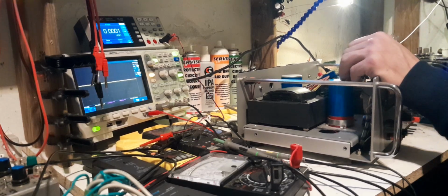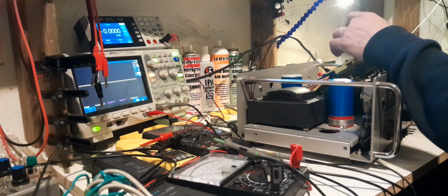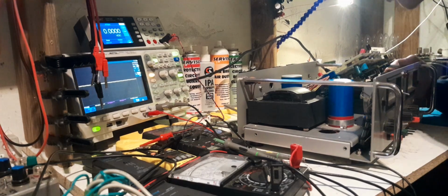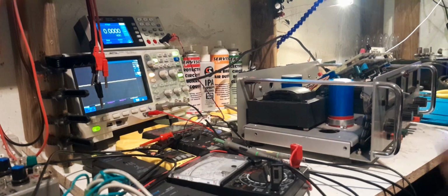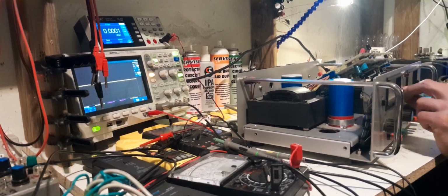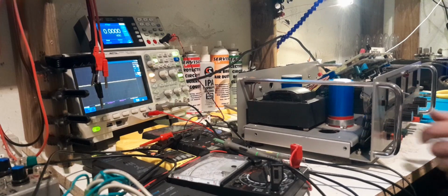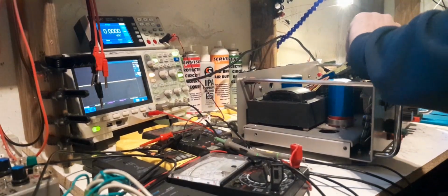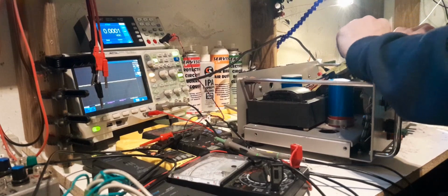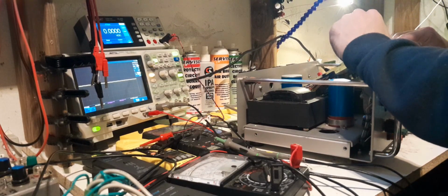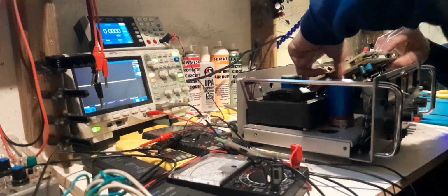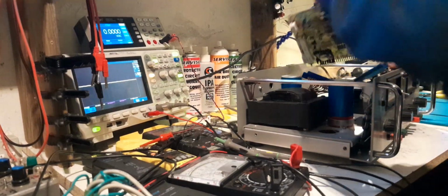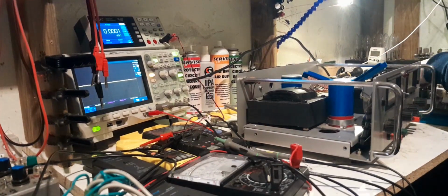But it is tied in with the voltage pot, and that does go back to one of these op amps. But it's tied in on the input side. Man, seriously? If I wind the voltage all the way down, it's that op amp. I know which one it is. I changed the wrong op amp. God, that's really bloody annoying. I'm pretty confident it's the constant voltage op amp I just clicked, because the voltage is just pegging straight up, there's nothing pulling it down.